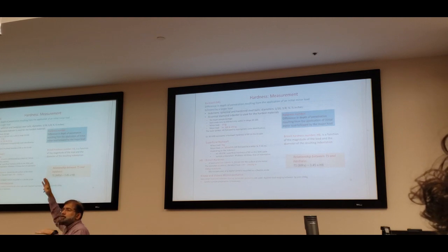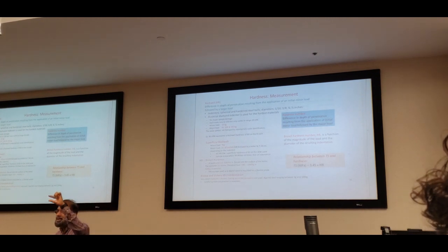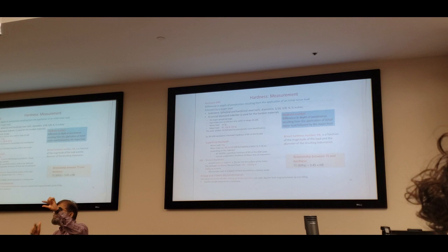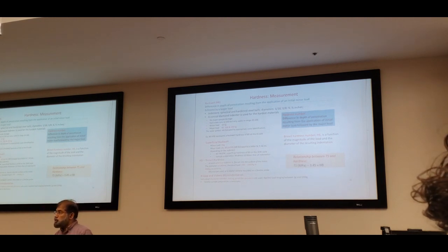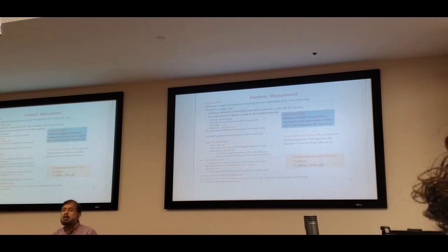Now you measure the difference in depth between the initial minor load and the second major load. You just measure the difference in the height. That is the first one.